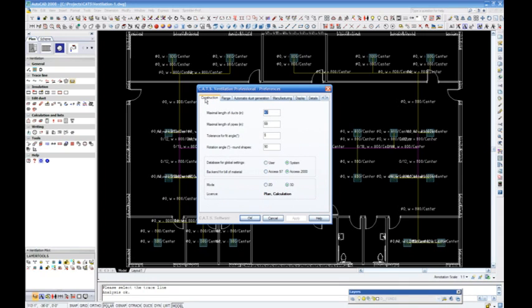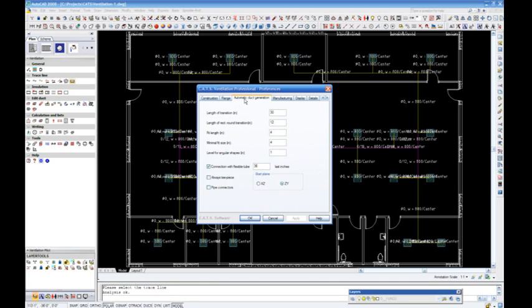C.A.T.S Ventilation Professional Preferences appears. Under Construction, we can set the maximum length of duct, round pipe, tolerance for fit angle, and rotation angle of round shapes. The others are software default. Under the flange, we have our settings on default. Under Automatic Duct Generation, we have the length of transition set at a maximum of 30-degree offset. Length of rectangular to round transition is 12 inches, and a maximum connection of flexible tube of 36 inches.